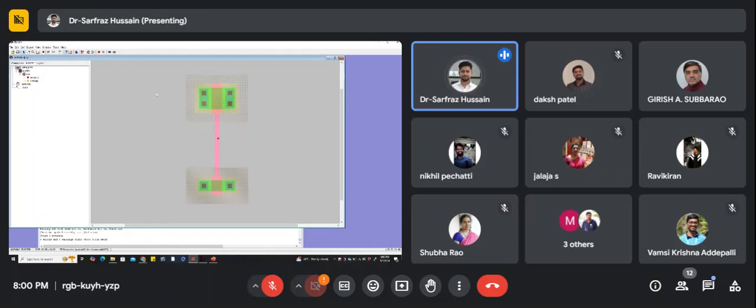So for the layout, you can connect the pins, you can connect VDD and all. After that, once DRC is complete, then you can do the ERC. In the ERC, we can actually check the wells. Checking the wells is also important. Now it will show an error because we have not connected any VDD pin and VSS pin, but we have to do this ERC check.